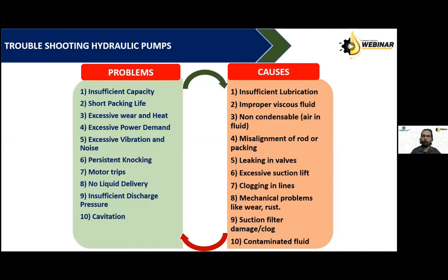So those are events, one in a blue moon. Normally when we see motor is tripping, it means there is high discharge pressure or insufficient suction pressure. Either suction strainer got choked, or discharge filter got choked, or motor is overloaded due to continuous draining of fluid from PRV or FCV.